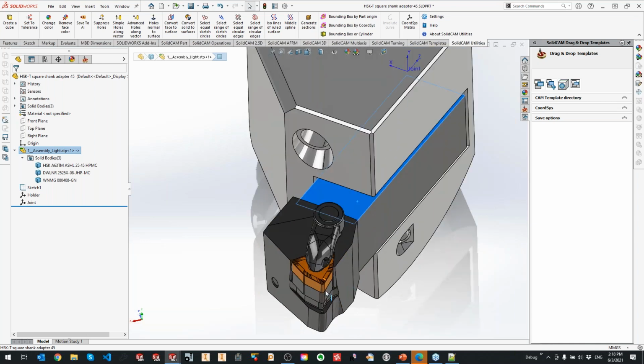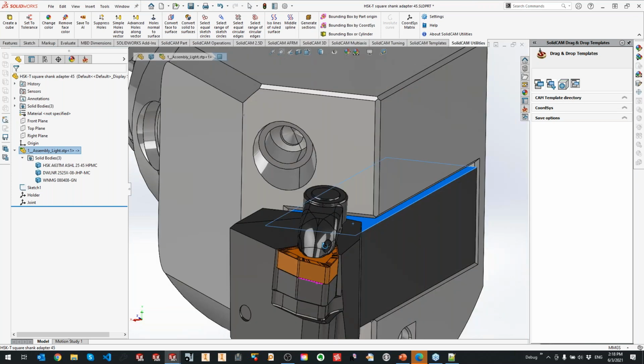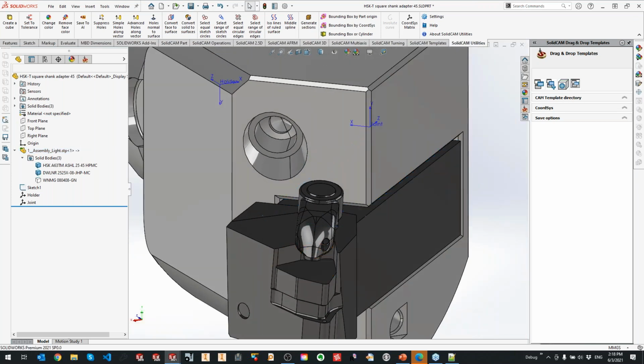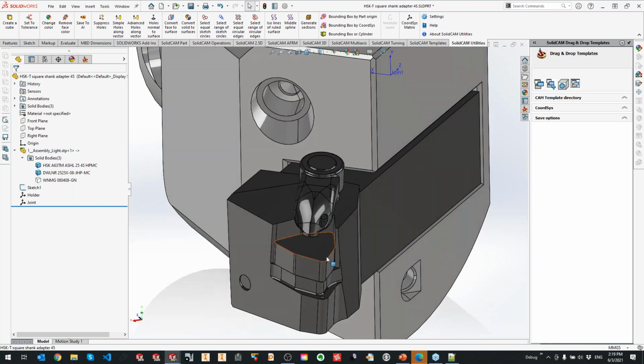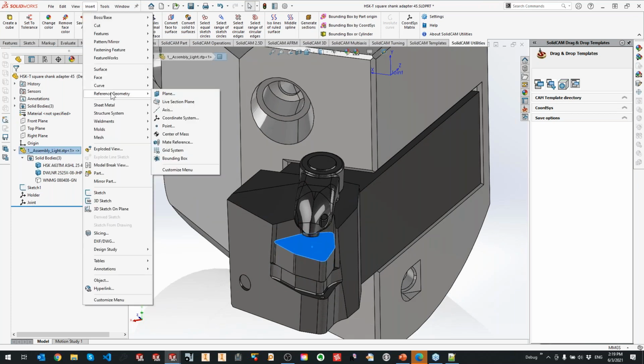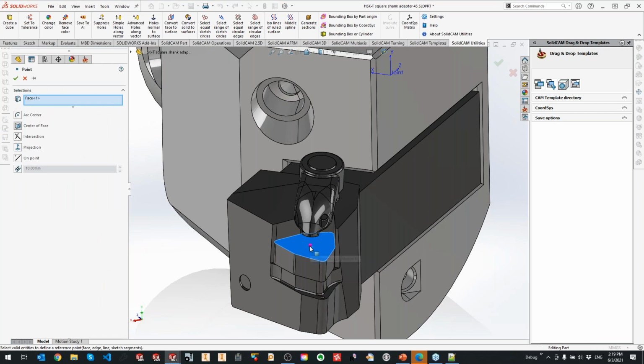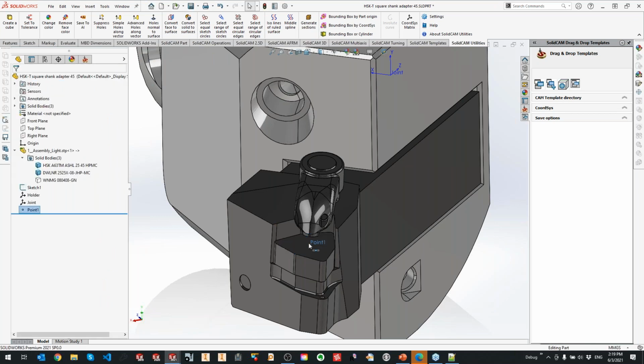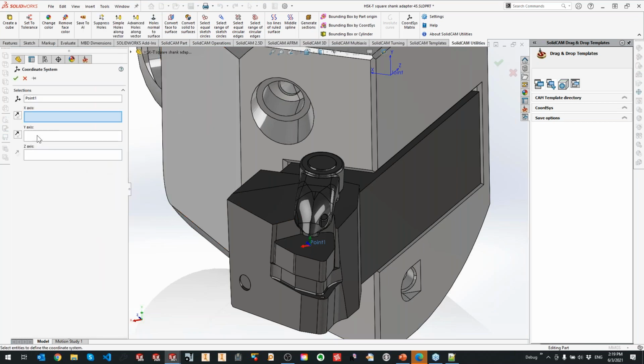The next thing is to put the joint coordinate system of the insert. Now, the joint coordinate system of the insert is the crucial part and is different from the milling one. It is set to the center here, so I'll just define it in the center. I'll click OK. So this is my joint point. And the main difference is that the normal plane is not the Z axis as we used to see in milling, but actually the Y-axis.